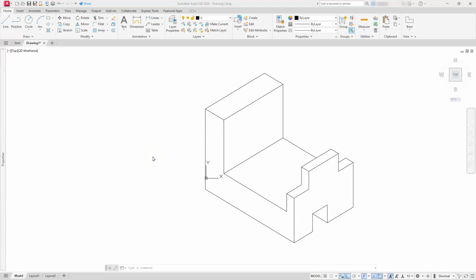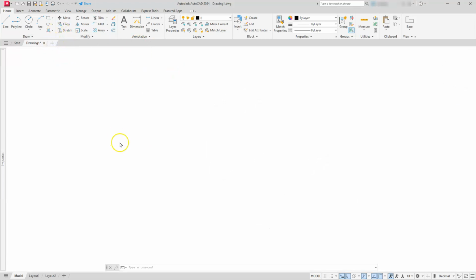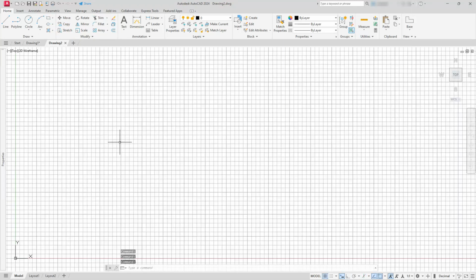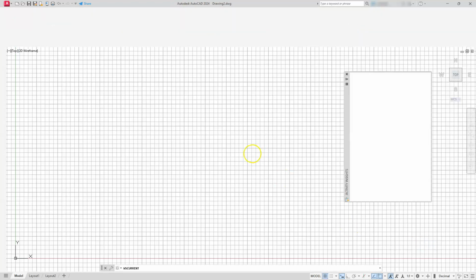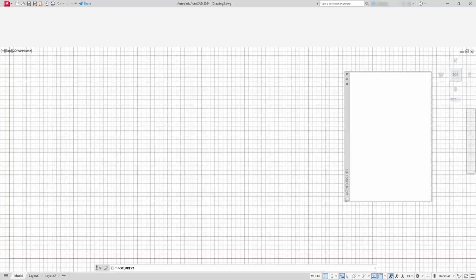Alright, so in AutoCAD, what I'm going to do is open up a new sheet, which is just clicking this plus here. And once I do this, I need to tell AutoCAD that I'm going to be doing some 3-dimensional things here. So the way that we do that is that I'm going to select this little gear, this sprocket, click the fly-out next to it, and then jump over to 3D Modeling. You can use the 3D Basic one. It has a lot fewer commands to use. But I like to use 3D Modeling as I can see all of the commands that I typically might want to use. So I'll select 3D Modeling. Give it a second and your ribbon should change over.